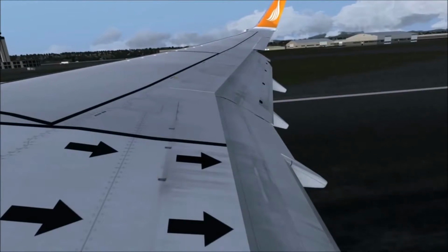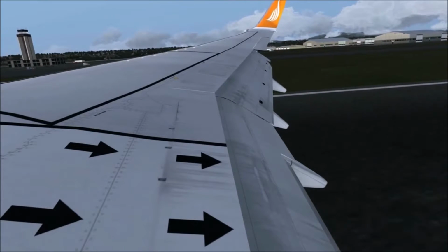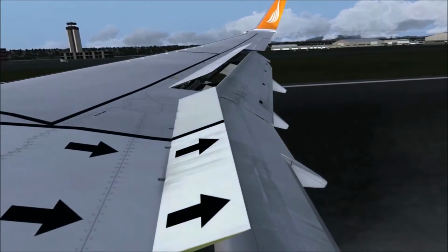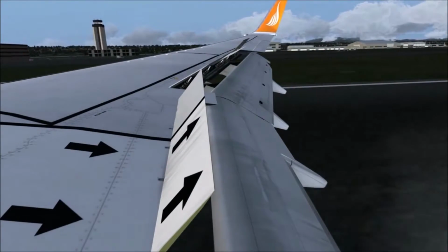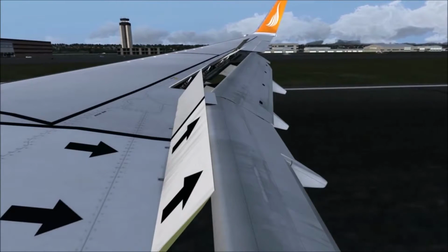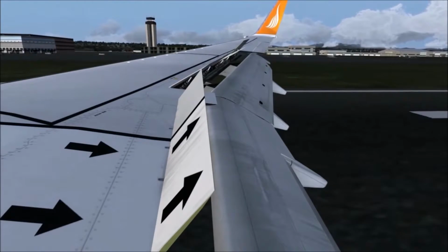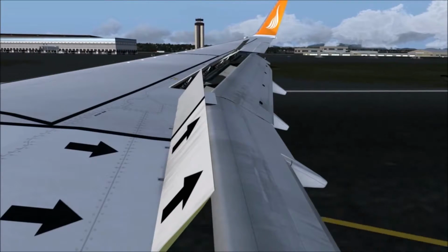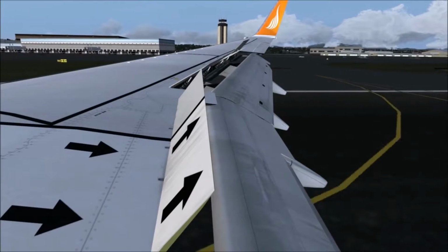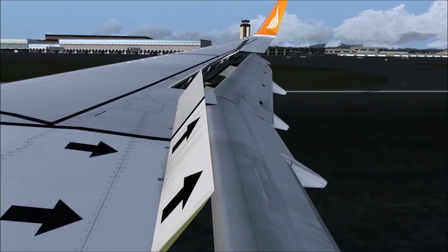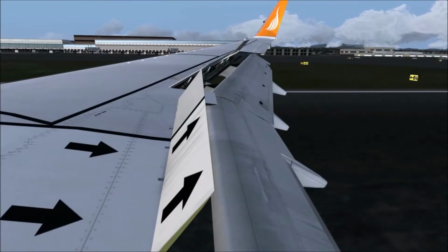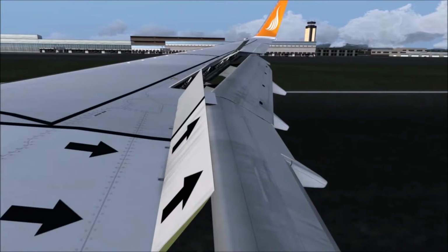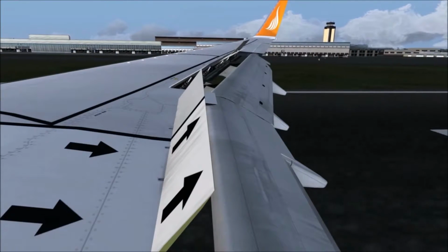When the aircraft is on the ground, the spoilers have the following function. As a rule of thumb, the speed at which an aircraft touches down during landing is a few knots higher than the speed at which it would have taken off. This means that when the aircraft touches down, there's still a little bit of available lift in the wings. For this reason, spoilers deploy upon touchdown in order to completely destroy the excess lift and allow for the landing gear to have better adherence to the runway. This allows the wheel brakes to perform better and therefore reduce the stopping distance of the aircraft.